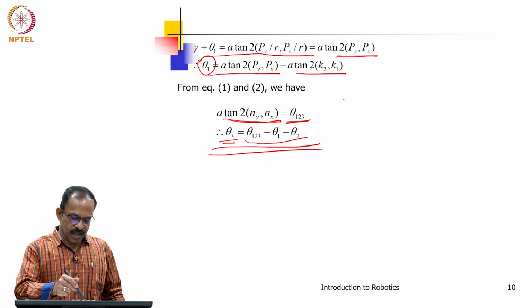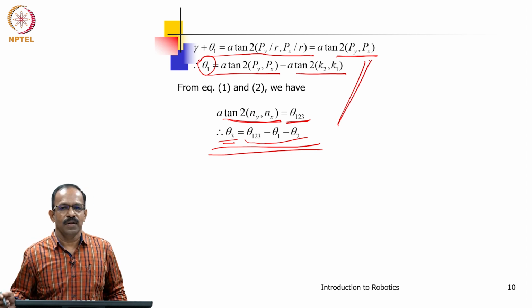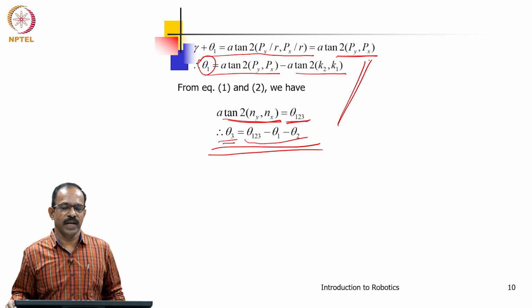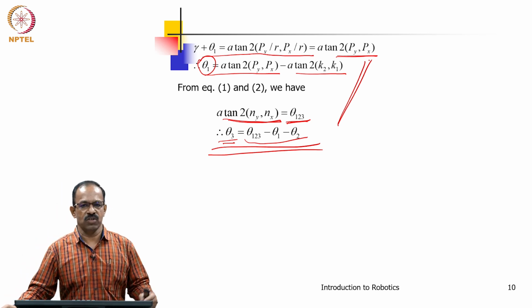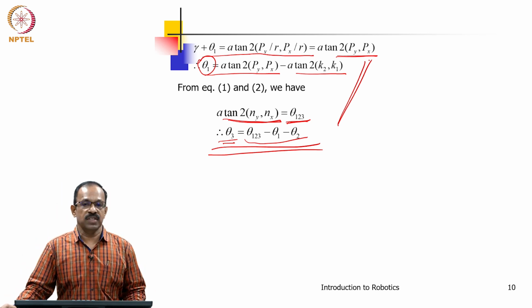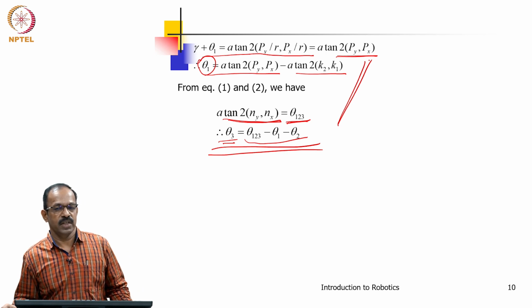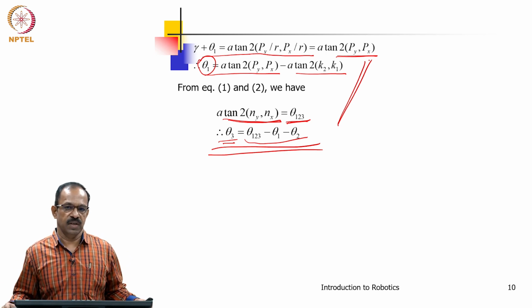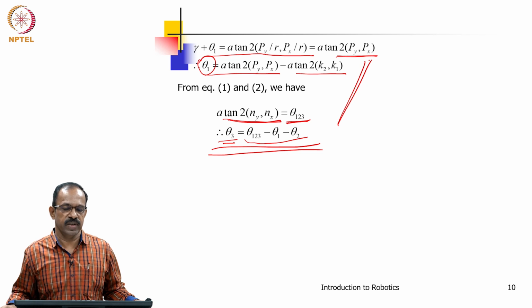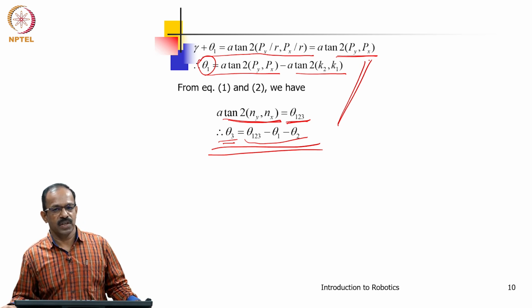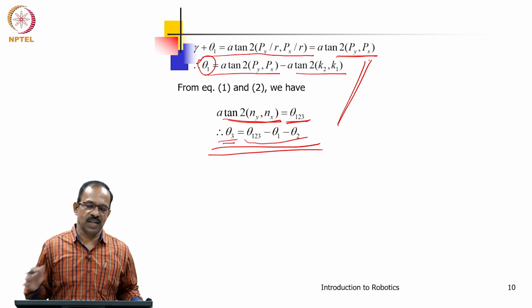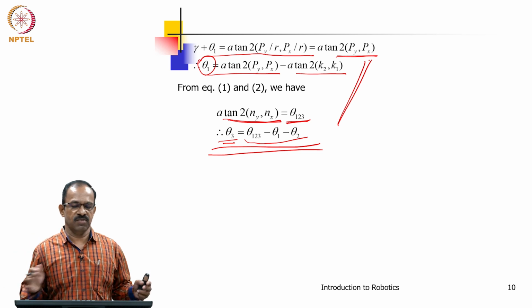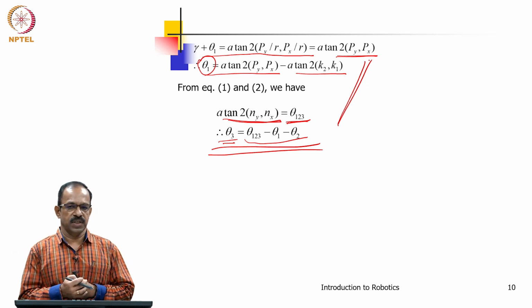Now, you can see that there are a lot of substitutions we did to get this. So, one question will be how do we know what to substitute, how do we actually solve it. This is one challenge in inverse kinematics, because for each manipulator the equation will be different. There is no standard equation that you can see for the manipulators. Depending on the number of degrees of freedom, depending on the configuration of the robots, the relationship of Px, Py, Pz etc. will be completely different.